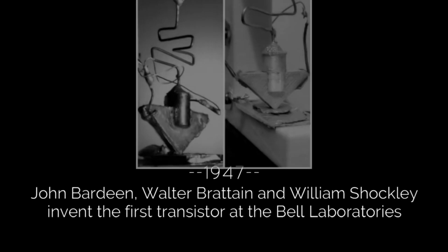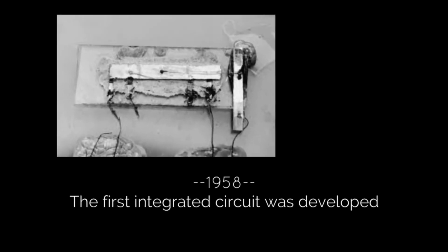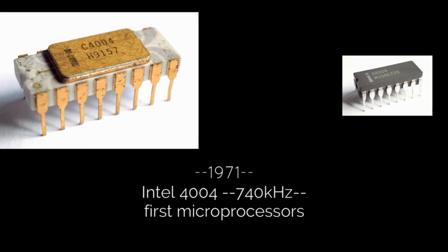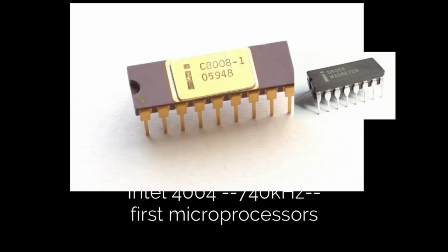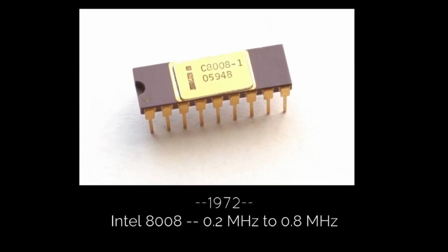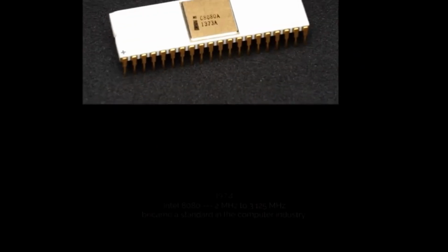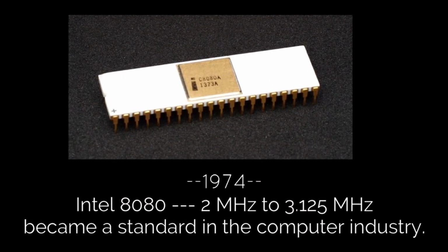And we will explain how data moves between the CPU and RAM through a data bus and address bus, detailing the role of registers and the program counter. The evolution continues with the introduction of the Intel 8008 in 1972, featuring 8-bit architecture, 14 bits of address capacity, and indirect addressing capabilities. It also touches on interrupts, a mechanism allowing hardware signals and events to pause program execution.